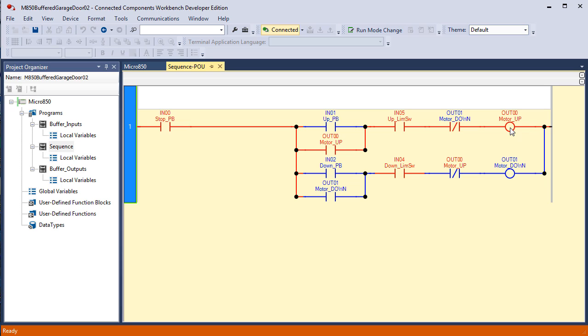Then, just because the voltage gets to the coil on the starter doesn't mean that the coil on the starter has continuity and is creating a magnetic field to pull the armature down and close the contacts. Or it doesn't mean that even if you pull the contacts down, that one or more of them aren't burnt or damaged with carbon tracks, build up carbon, and they're not making good connectivity. And even if they are making good connectivity, that doesn't mean that there isn't a wire or two broken between the contacts on the starter and the leads on the motor. And even if that's all good, that doesn't mean the motor's working correctly.